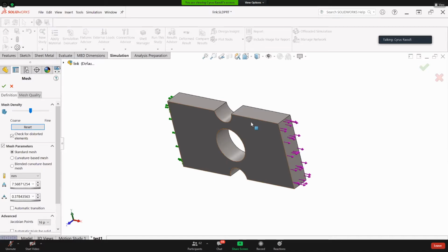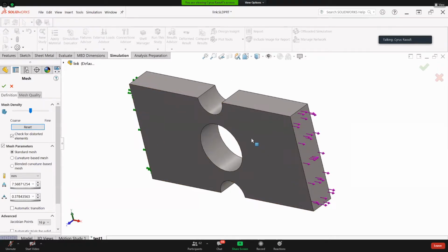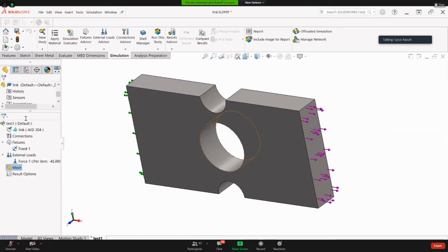The default for now, I'm going to talk a lot about this one, but chapter 3 is completely about meshing and sizing and type of elements and so on. There are so many things related to this topic. But for now, keep in your mind that if you don't touch anything, the default element for a solid part, if you are using solid, which is here, as you see, we have solid, that represents the solid element, then the default for solid is second order element, which is called TET elements. I'll talk about TET elements, but it's second order. That's a default if you don't touch anything.